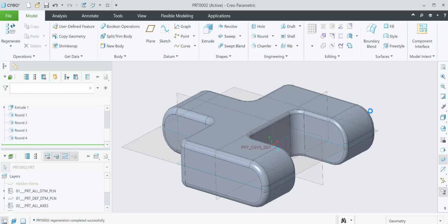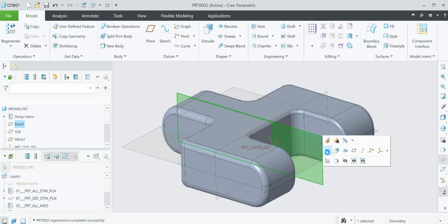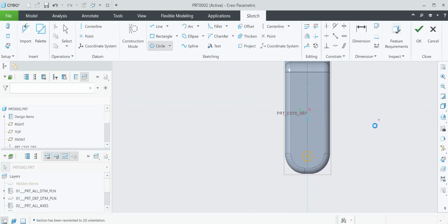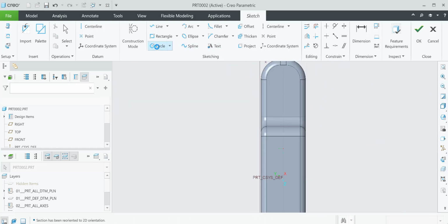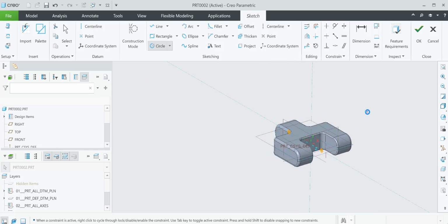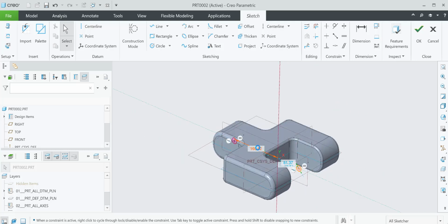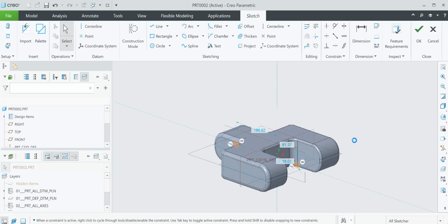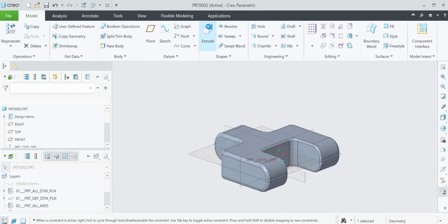How else can I put in a hole? Well, at Design Engine, we like to teach people to use surfaces as tools. So I could square up on this geometry and literally sketch a circle and literally extrude a hole. And now you've got a parametric geometry. The strategic advantage of that is it's less features and it's really quick. Here, let's just do it real quick so you can see it.